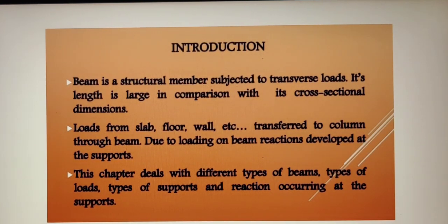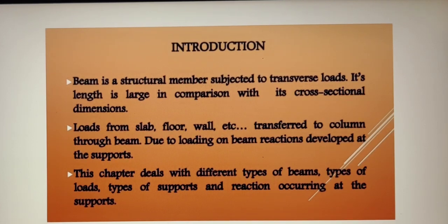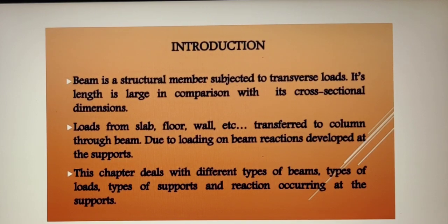Now we will see in detail what a beam is. A beam is a structural element which is subjected to transverse load, that is, load is applied perpendicular to the axis of the beam. Second, its length is large compared to the cross-sectional dimensions.